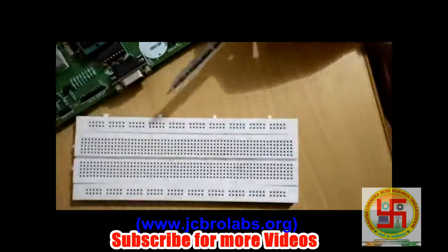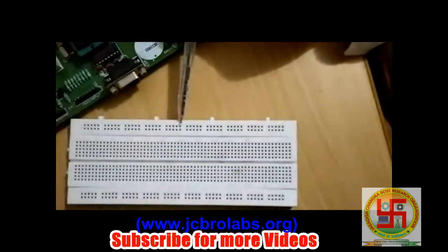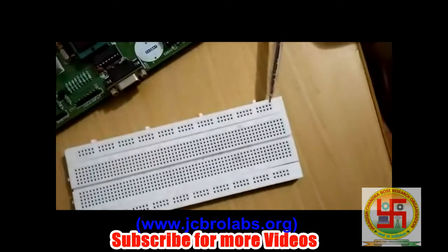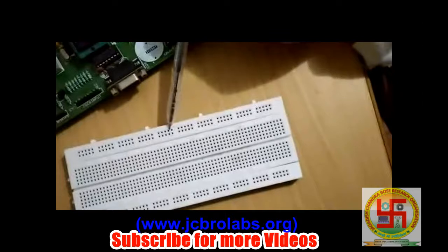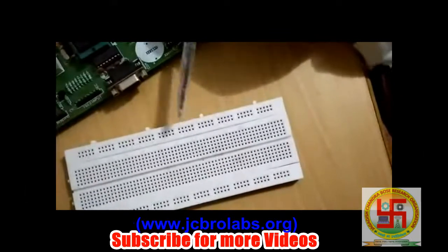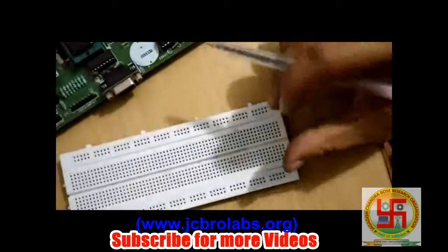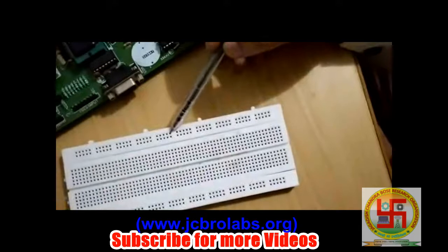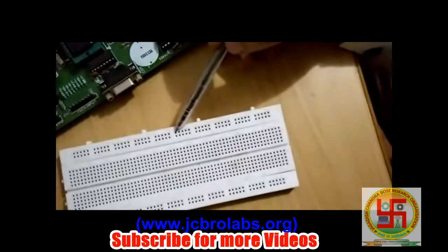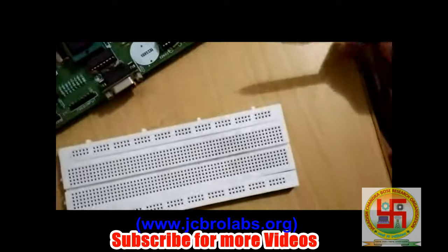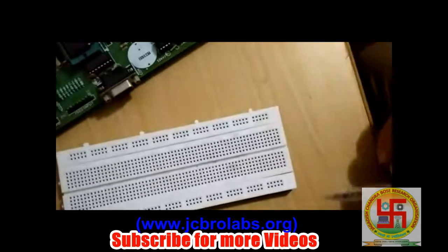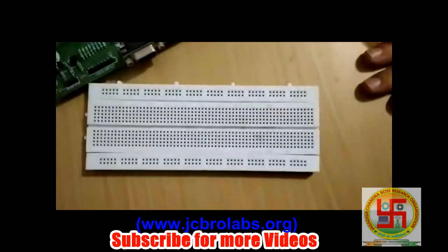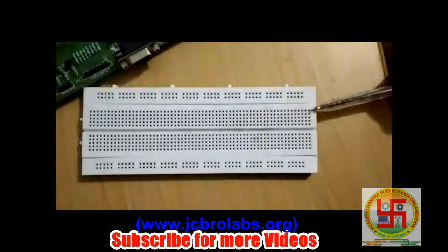Now further, this breadboard is divided into 2 parts. That means this is shorted up to here, and this is shorted up to here, and these two are not connected to each other. So if we want to make a complex circuit which needs power supply here and here, we need to provide a small jumper wire connection from this side to this side. So this is a brief intro of the breadboard, and now we will implement a small circuit.